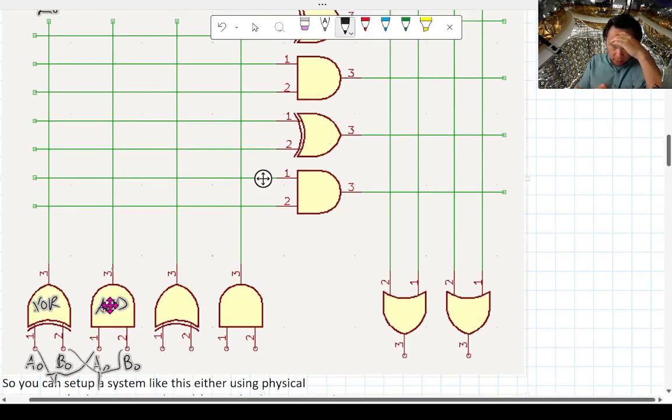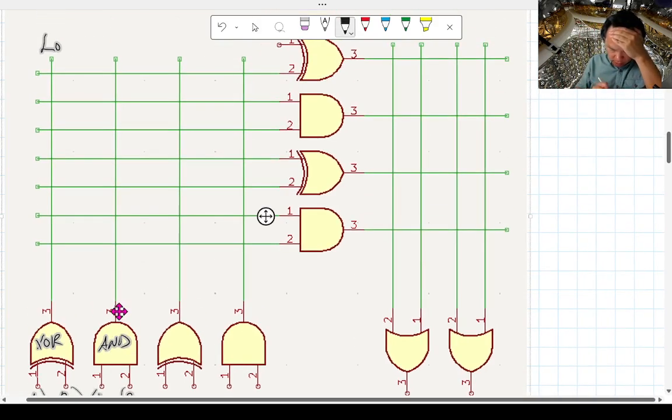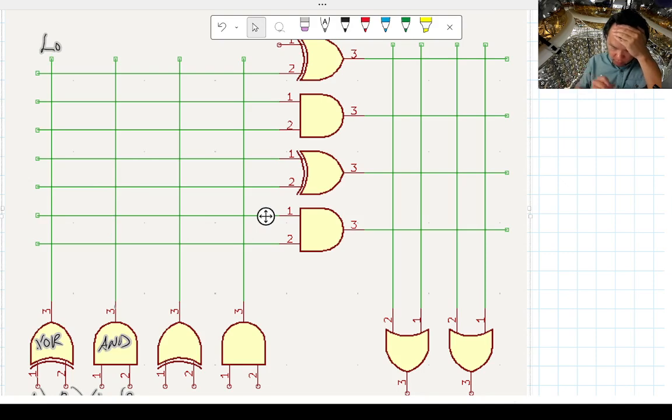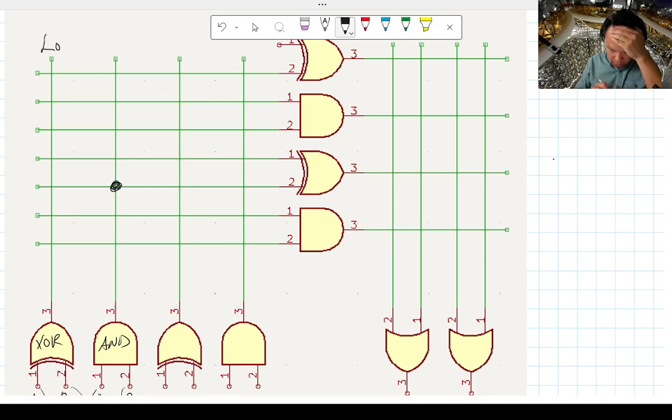The AND gate, if I remember right, the AND gate goes into the second layer of XOR gates. So let's go there. So we need to find an XOR gate, go up this line until we find an XOR gate. Let's put it here. So that's the right here, a bit. Okay. So if we make this connection, basically what we did is we make the output of this AND gate into the input of the second layer of XOR gate.